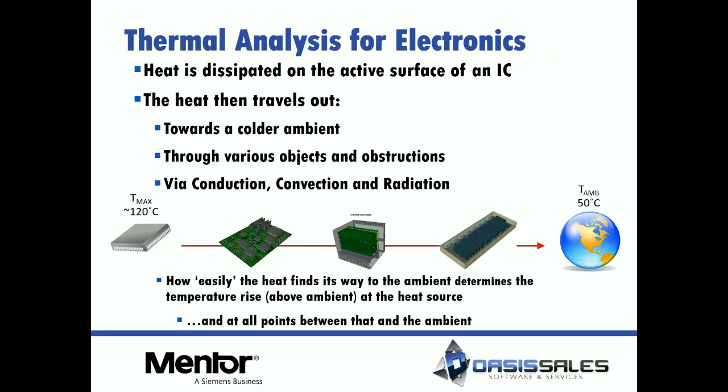So when it comes to electronics cooling, what's actually going on? Well, there are two main hard temperatures within electronics cooling, a min and a max. Typically, the maximum temperature is what we call the junction temperature within the package, and this is around 120 degrees C or 260 degrees Fahrenheit. After this temperature, commercial chips tend to fail. They will burn themselves out, and obviously the logic won't work anymore, and then you've typically got a dead product.